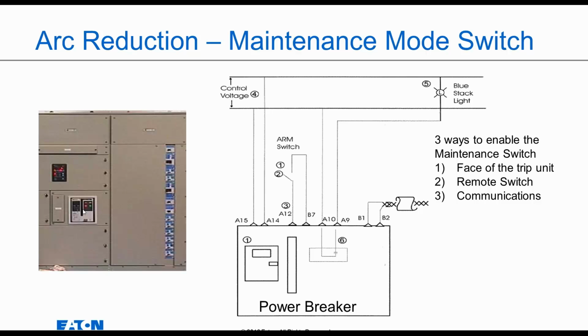Well, if you shut down this breaker, it shuts down all these feeders feeding whatever load it is. And if you had to work on it live, then you could put this breaker in the maintenance mode, and that protects all that downstream to all of these feeder breakers. So now you can work on this with the knowledge that you're in the maintenance mode. It's going to be a much reduced level of arc flash should there be an accident that occurs.